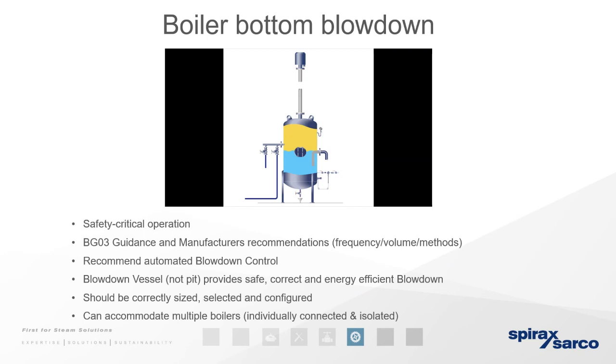until it can then be discharged to town effluents at temperatures of no greater than 43 degrees Celsius. Having said that, it is generally about a 2-inch valve that you will find underneath the boiler, and therefore it's recommended to only have it open for 3 to 5 seconds, as anything longer will most likely just be a discharge of good treated hot water, which will be a waste.